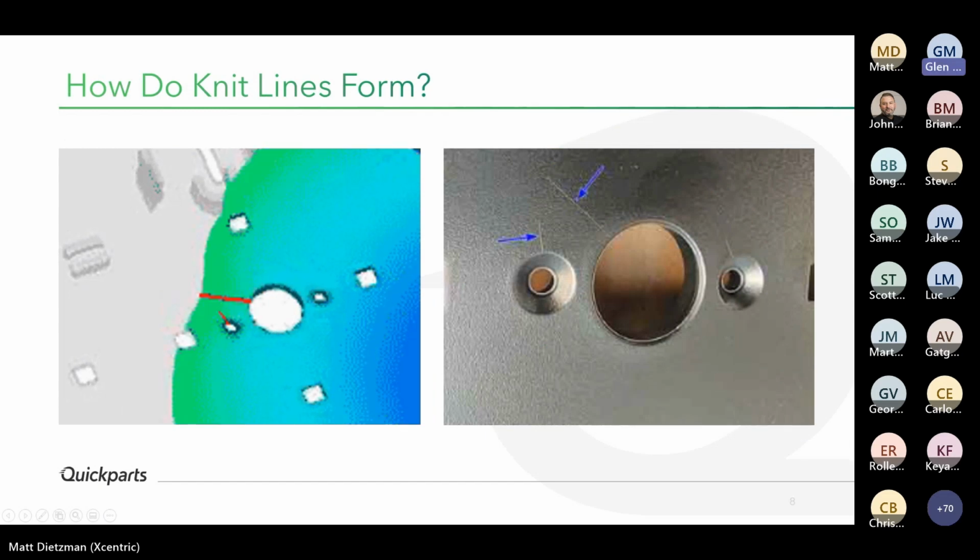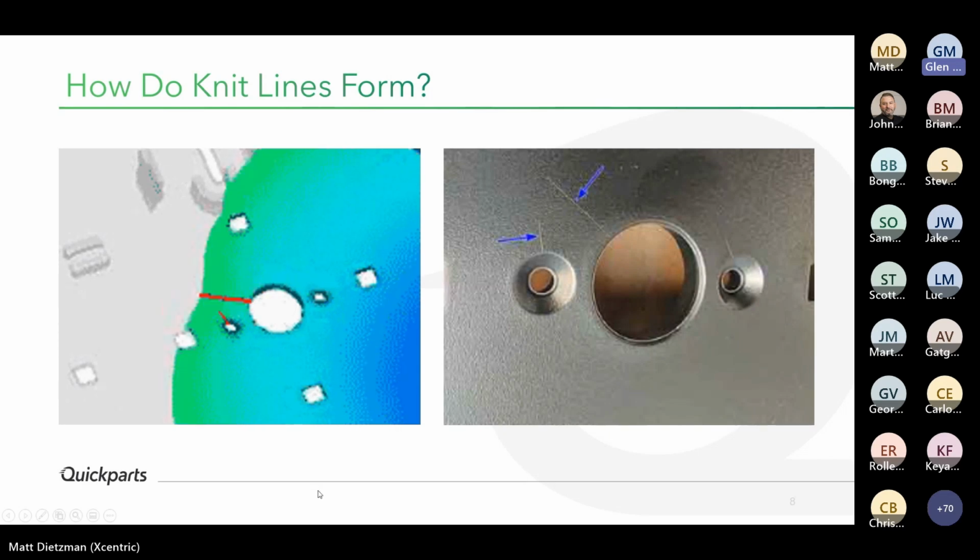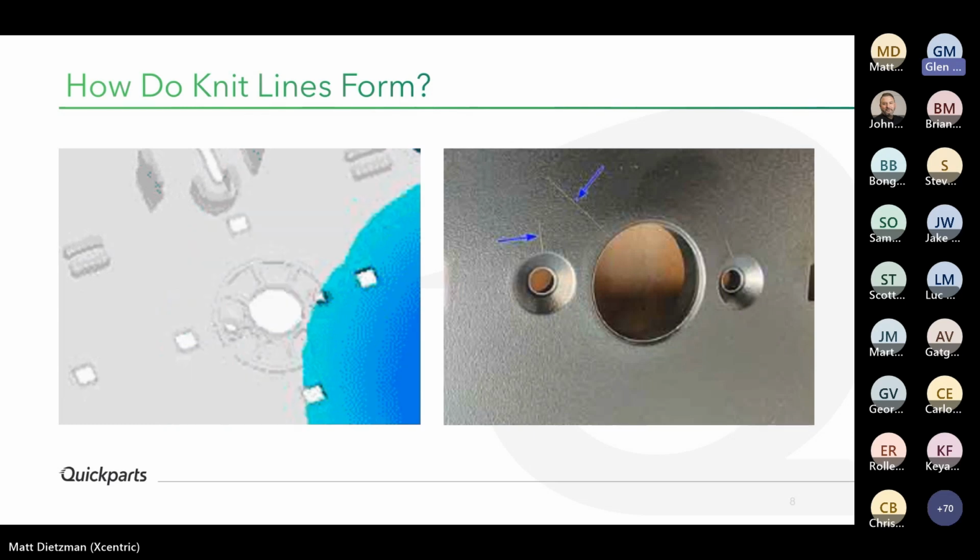That's a good animation right there. We're flowing around that hole, and you can visibly see where that knit line forms. That's part of a mold flow right there. That's showing you how this material is going to go through your part in simulation, and you try to make adjustments and predictions based on that. But it is a simulation, so it's the best guess, so to speak.